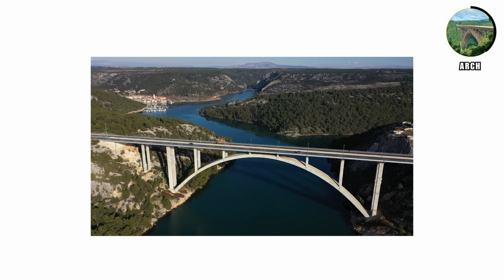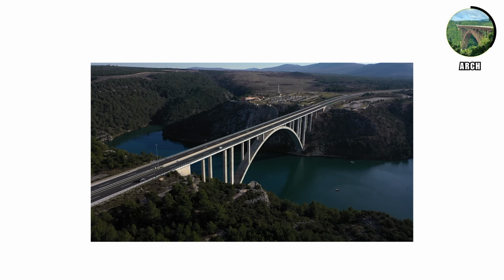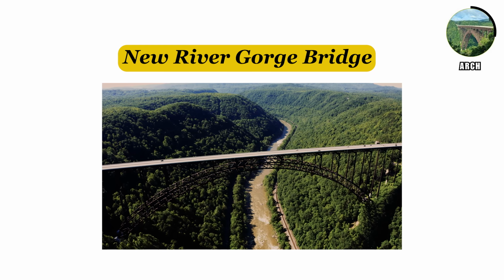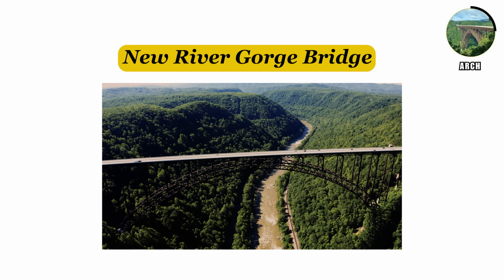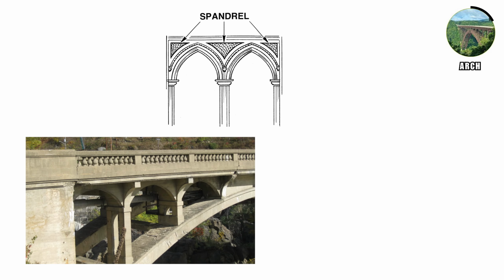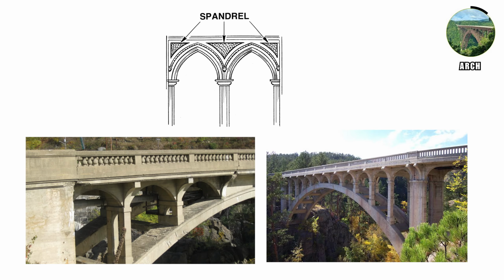Deck arch bridges place the arch below the roadway, with vertical supports transferring the deck load down onto the arch. The New River Gorge Bridge in West Virginia is a deck arch where traffic rides on top of the curve. The area between deck and arch is called the spandrel. Open spandrel bridges use columns to transfer loads, while closed spandrel bridges use continuous walls.